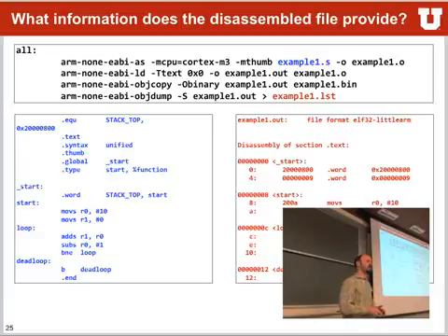It's actually telling the microcontroller that whatever is at this location is a thumb instruction, not an ARM instruction. So if this were 8 in here, it would mean that wherever you jump to is an ARM instruction. And if you ever try to do this on your Cortex-M3, you will get a hard fault, because the Cortex-M3 cannot execute ARM instructions. We will see when this is added as +1 or when it's not. Sometimes you don't have to do it because some of the jump functions do not switch your execution mode, but others you have to add +1 to the memory location, or else you will get a hard fault. Sometimes very confusing to figure out what's going on.